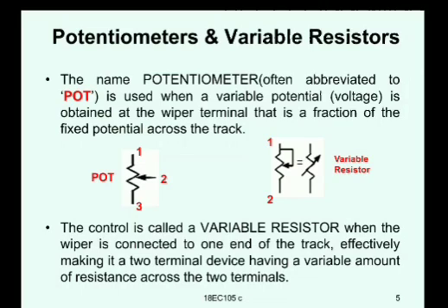That means you apply a voltage V across the two extreme terminals of the resistor, and the voltage available at the variable point, terminal 2 in the figure, will be a variable potential. As you go on changing it, you will be getting a different pickup for the current position at that place. So that is how the potentiometer is working.